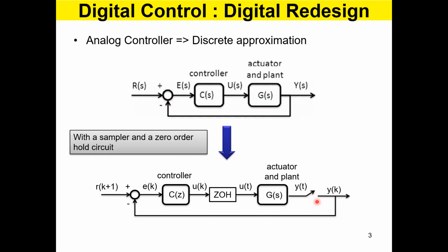So now, whatever happens to YT is not observed until this switch is closed. The switch is closed at regular intervals. If you say 1 hertz, one time every second it closes, and at that moment you read the response. Let's say the switch operates for 1 millisecond at a 1 hertz sampling rate.